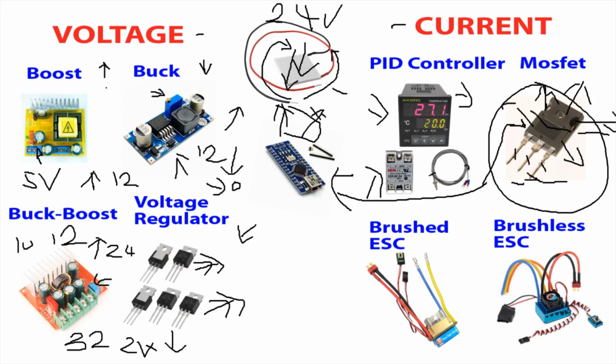You have to use resistors, and it's more complicated using multiple MOSFETs. But that does depend on the load, of course. If it's not a huge TEC, then this is the simplest and most cost-effective way. You also need resistors. It's not like you can just use a MOSFET with an Arduino.